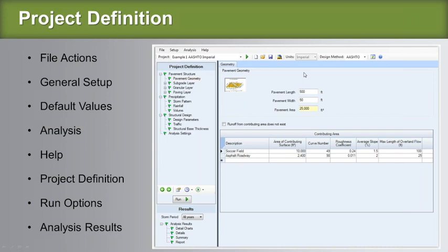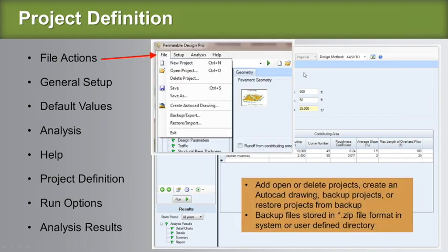We need to know about roughness coefficients. You select from a box and it will tell you whether it is a field, a hard surface, and so on, and it will give you a number that you can use, or you can enter your own. Then we have information about slopes, how much slope is on the area that comes to my permeable pavement, because that will dictate how fast the water moves. We also have the length of overland flow, an average of where the middle of your roof is, for example. So how long is it going to take to get to the permeable pavement system?